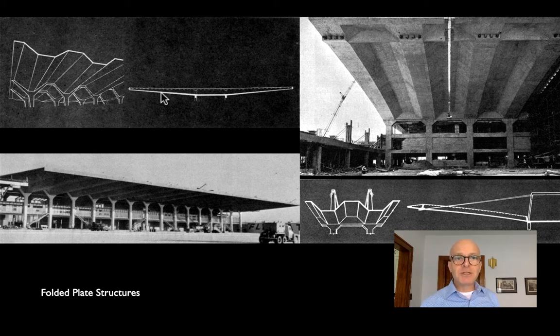But if you look closely, you can see that that cantilever shape isn't solid. What we're looking at, the light line on the top, is the profile in elevation of that top fold. And what we're looking at the bottom is the section cut through the bottom of the plate there. So again, we've taken a very, very thin element that couldn't probably hold its own weight over that cantilever span. We've given it those folds, sort of tricking it into thinking that it's a much, much deeper structural element.